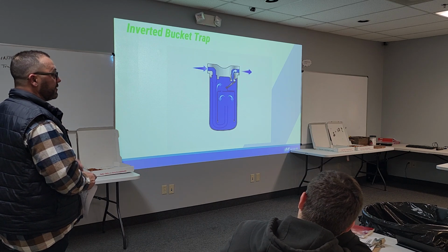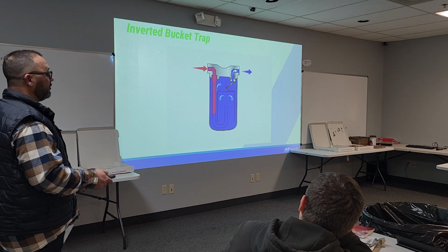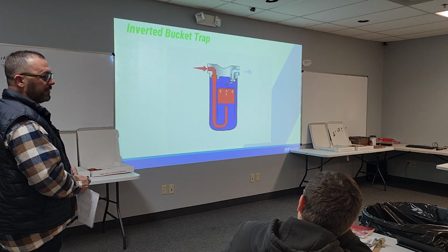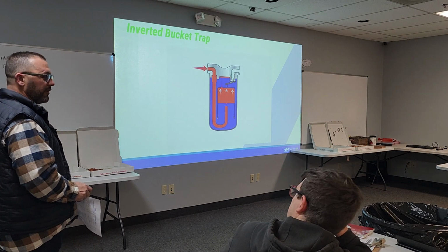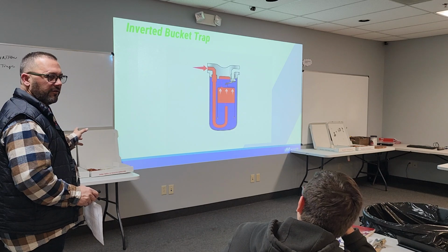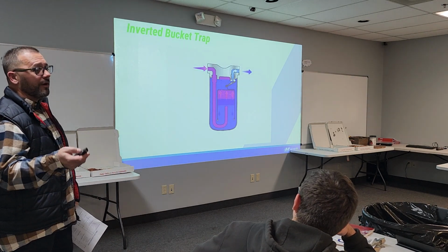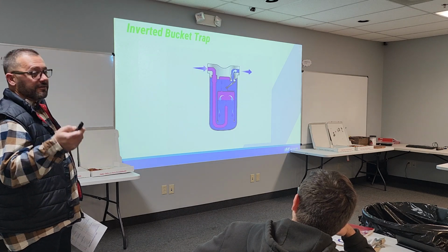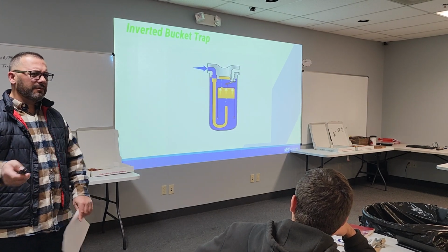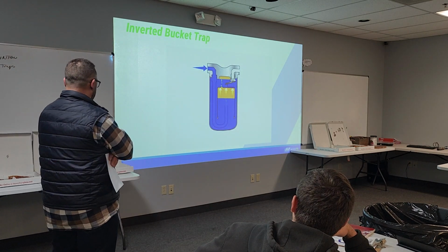So if you're in a condition where there's a bucket trap at a plant or wherever you are, and it sounds like it's blowing steam, a lot of times what you want to do is go upstream, close that valve, give it a few minutes, and then open it slowly. And if that fixes it, we could spend 3 hours on troubleshooting traps and then talking about steam trap surveys. And you see a lot of steam trap surveys up here, the bigger steam users. Yeah. That's too bad.